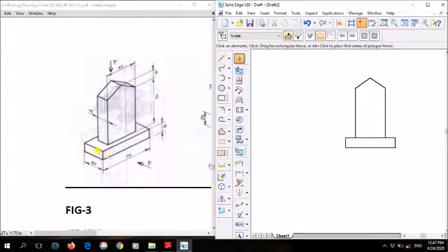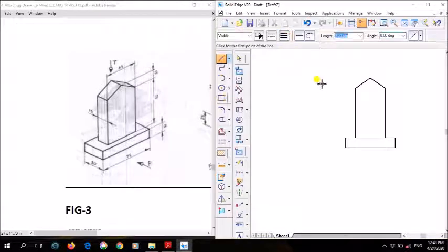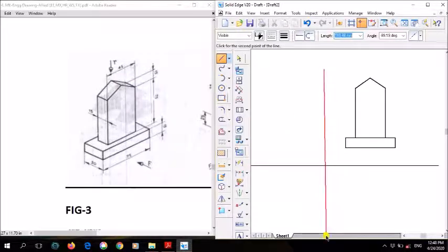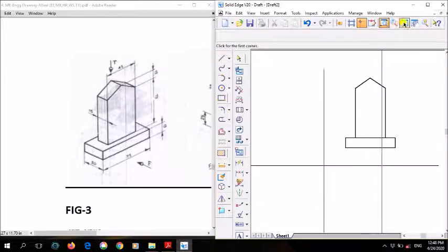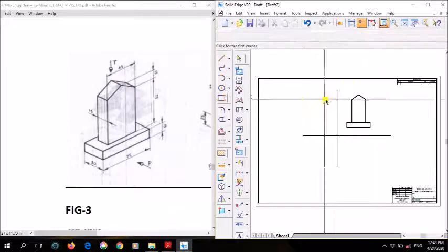In front view, this plane is visible and this plane is visible whole. So we have drawn the front view. Next we'll draw the right view. This right view is drawn on the left side. Before that, using thin line, draw the axis line. Leave a sufficient gap here and draw the axis line. Same way draw the axis line from here to here. Clear? So like this, draw the axis line.